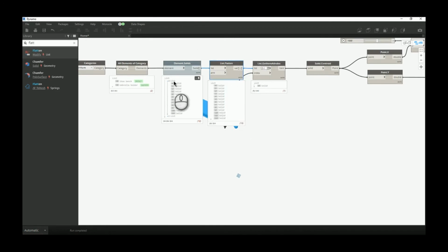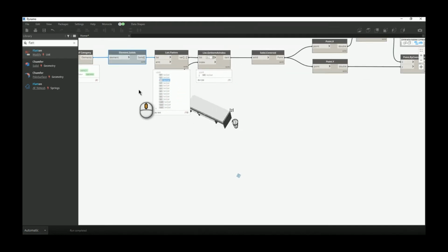Basically, if you have some levels and you want all elements to be in the same level, and you don't want to delete anything, you just connect that to the list flatten, and now level 1 and level 2 are just one level, and as we said, we need the element with index 2, nothing is changed regarding that, so now everything is okay.